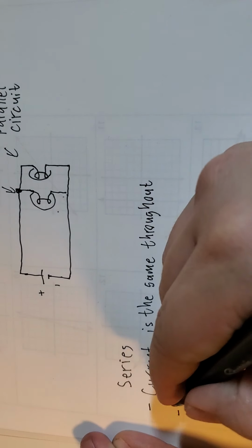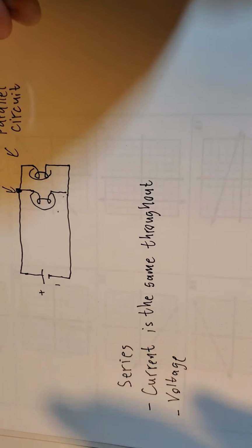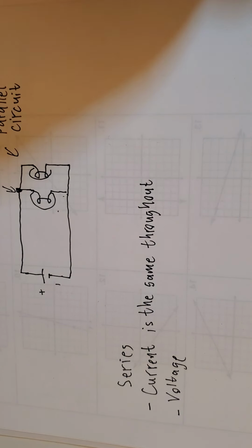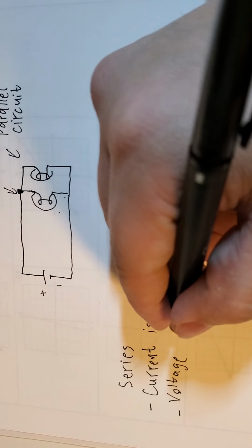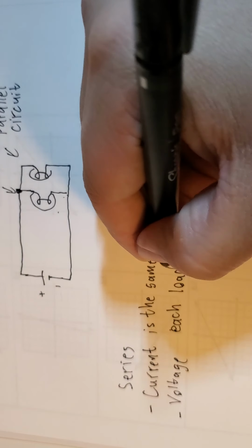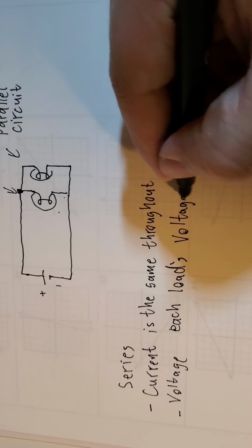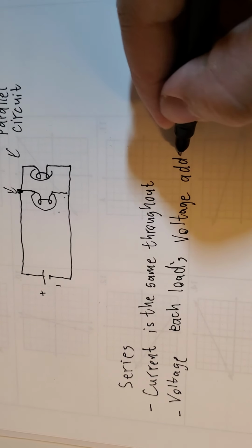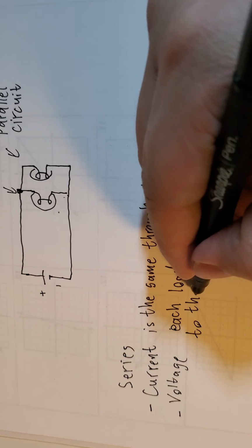Now, voltage will act a little bit different. Okay, so every device, every load is going to require some potential energy to work, right? And so what we're going to say here is that for the voltage, each load's voltage adds up to the total voltage.